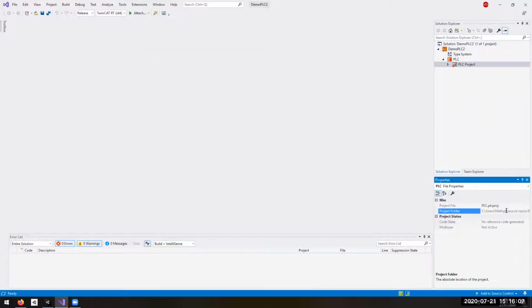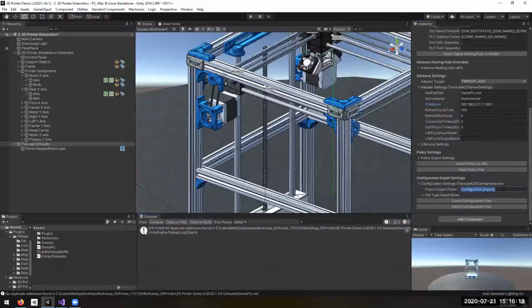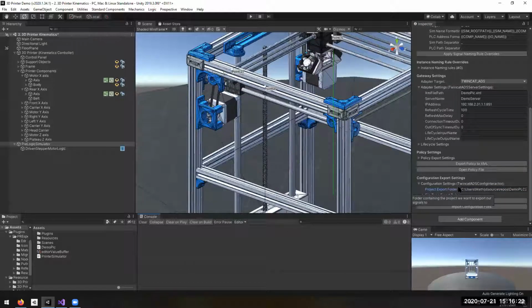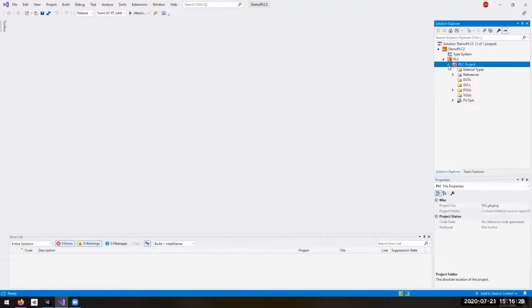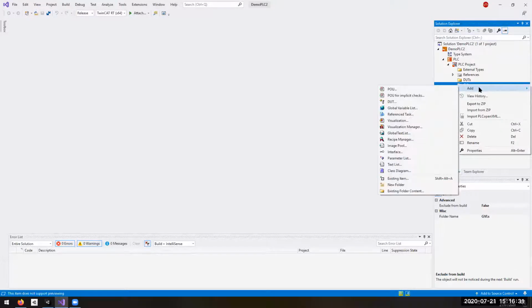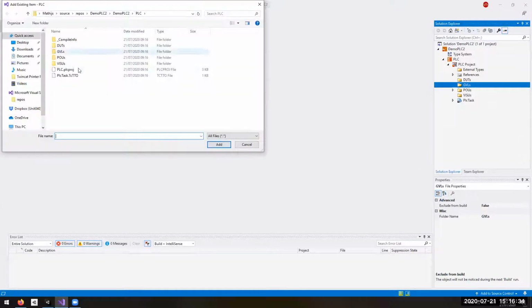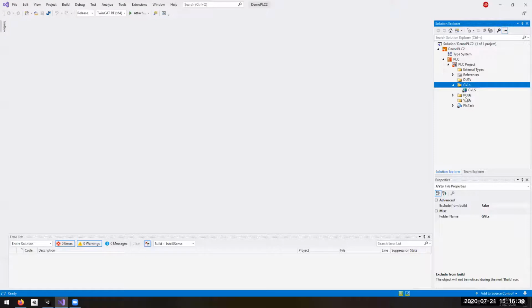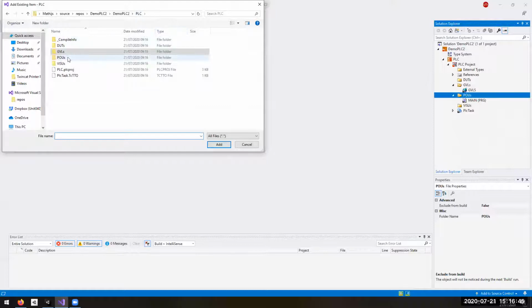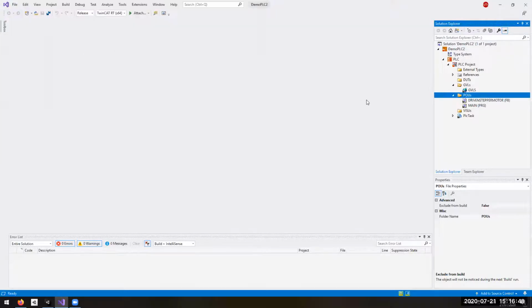Okay, and then here in TwinCAT it generates a folder destination for this project, and we need to input that folder destination in here, because next thing we're going to do is export our configuration files, and it just did. And what it does is it writes files to our TwinCAT project, and our global variable list here, we can now add an item which has just been created by our team. That's the GVLs here. Let's add this and do the same thing for our POUs. The driven stepper motor, there it is, it just generated it.